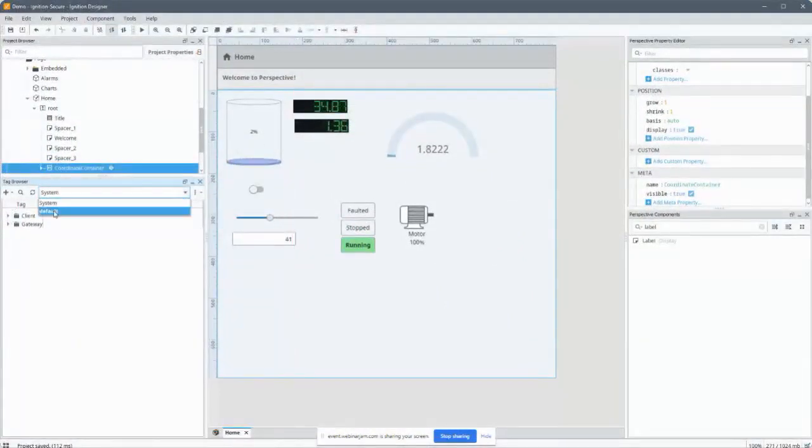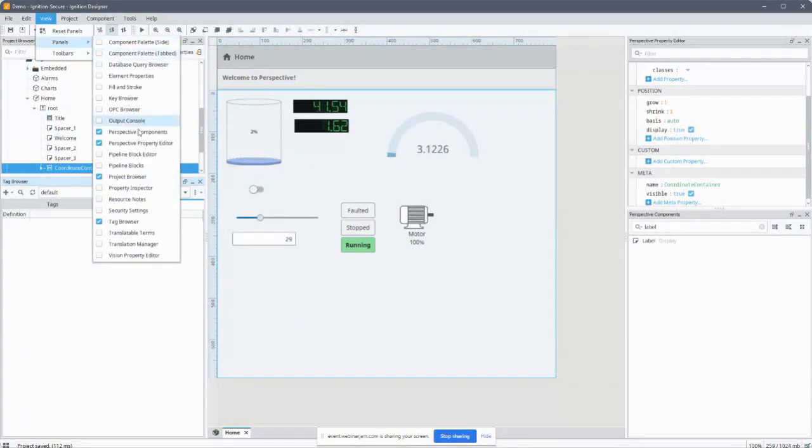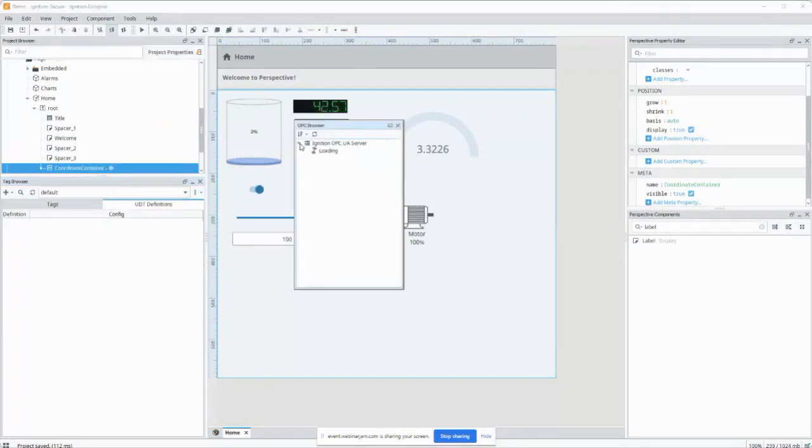Now, what I wanted to mention is that not only can we build straight tags, we can build objects and reuse objects over and over again. So I'm going to quickly show you an example of this, where I'm going to go in here and browse again the OPC server and see there's our dairy. And here's overview, and I've got 8 motors. The motors are the same. They have amps and HOA, 2 tags.